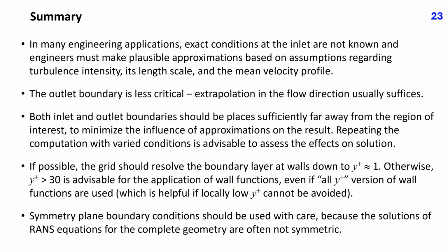Here is a summary of this lecture. In many engineering applications, exact conditions at the inlet are not known, and engineers must make plausible approximations based on assumptions regarding turbulence intensity, its length scale, and the mean velocity profile.